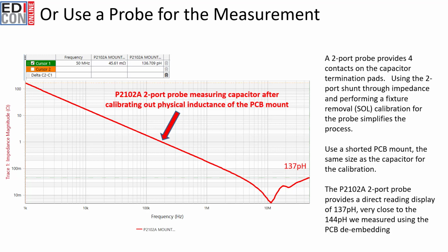If you are using a SPICE simulator, it's a bit more complicated. You could use an ideal short rather than the capacitor size short. This will create a measurement of the capacitor and the physical length inductance. However, it won't include the added inductance due to the precise port placements, i.e. the pad distance on the PCB. It also won't include the vias connecting the capacitors to the power and the ground planes. In other words, using a SPICE simulator prevents you from having the ability to include the PCB parasitics. This is where a tool like PathWave ADS allows you to be more successful.